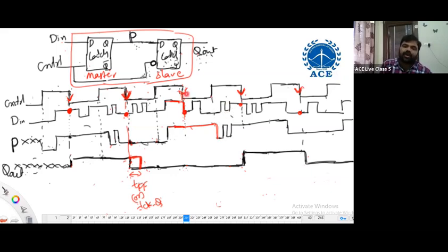But at this clock edge, what is the input we are expecting to capture? A logic 0. So when it is 1 here, obviously slave also follows. At this point of time, slave is getting enabled, slave is following master output. And after this it is getting disabled, it continues. What is the flip-flop output at this clock edge occurrence now? Logic 1. I hope you are able to write these waveforms correctly. Simply enable, disable, that's it.